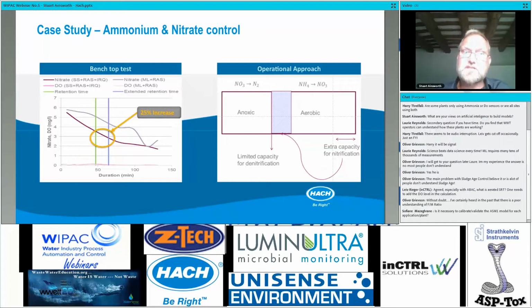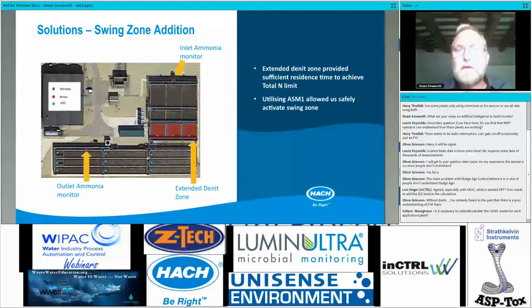Once we proved it in principle, working hand in hand with the customer and with the ENC, we decided that this would be a no-build, low-cost solution to get the plant to where it needed to be. By increasing the anoxic zone when we safely could, we would increase the retention time of the biological action in the anoxic zone to further reduce the nitrate levels to where we needed to be. That was the principle of the approach, and that's what we built into the system.